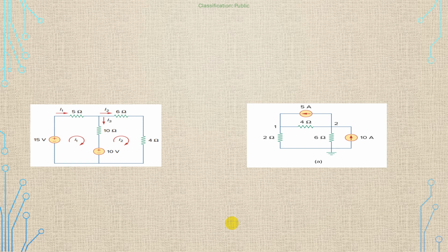I am assuming like this. So 10, I1 minus I2, because two currents are going here. So I1 minus I2, opposite direction. Next, current entering here, so it is plus 10. Okay, so one loop equation. Same, another loop equation here. Current is leaving because it will go up. So minus 10.